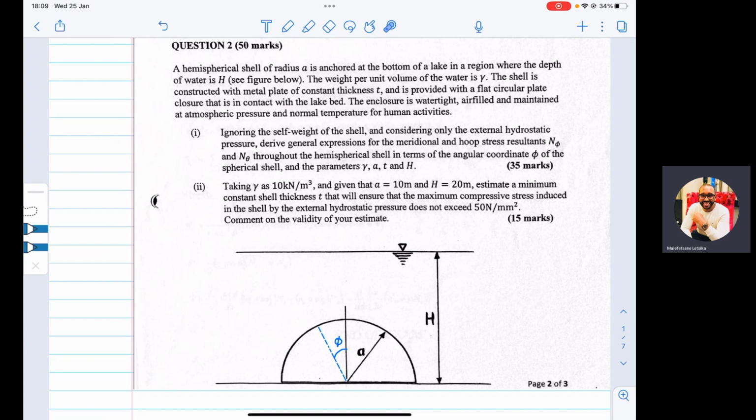But of course, given that shells are lightweight, stability failure becomes a problem. That's why sometimes we see engineers being concerned with buckling behavior, etc. But that's not for today. Today we want to analyze or derive the stress expressions that act in the shell.